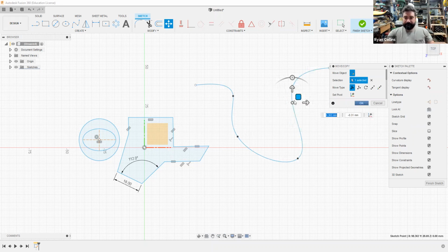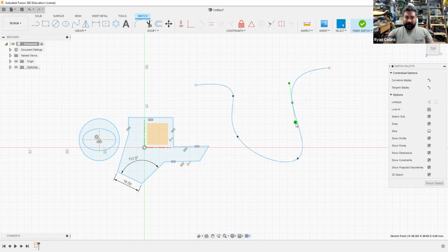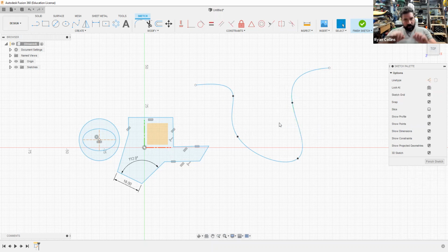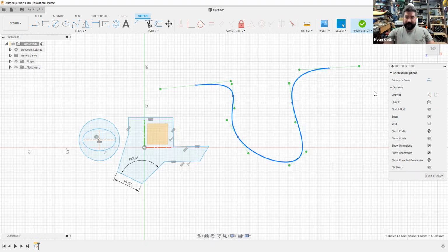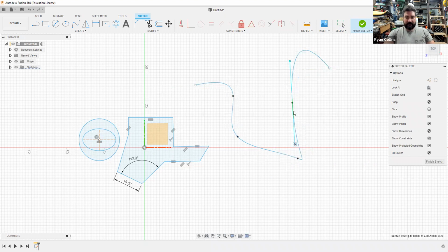Click OK. Yeah, sure, great. All right, click back on there, and now I have these handlebars. Well, what do these do? This is how you can tweak the curve of this line. Now to do that, to select that, you have to select the line again. So I can pick any of these. If I pick one, click and hold the point, I can drag it away and it makes the curve much larger. And I can also twist the handlebar and it'll twist that curve around. So this is how you can really manipulate some lines, make some funky lines, however you please, or you can trace around something. I'll show you that in a minute.